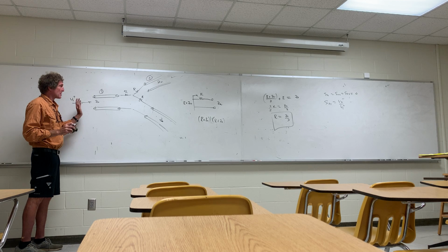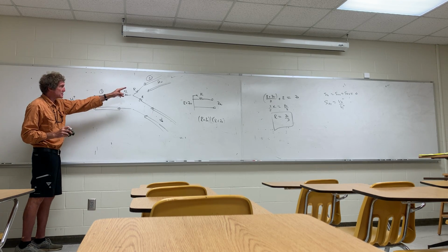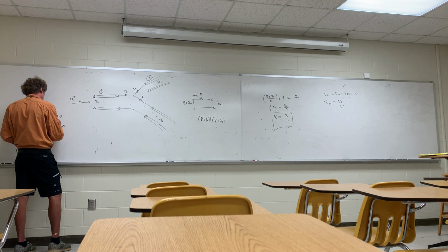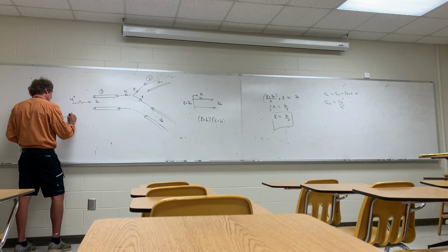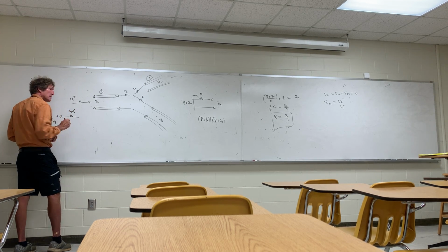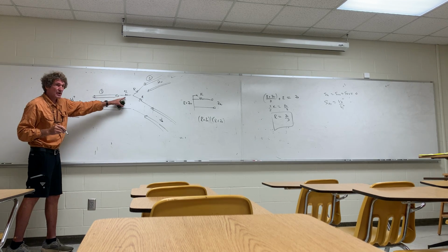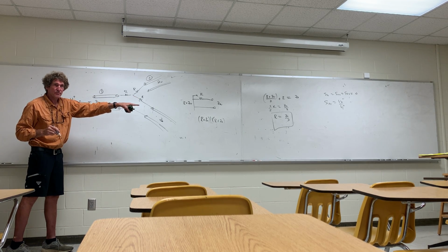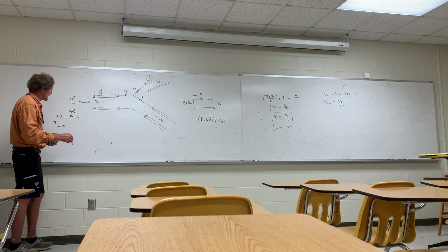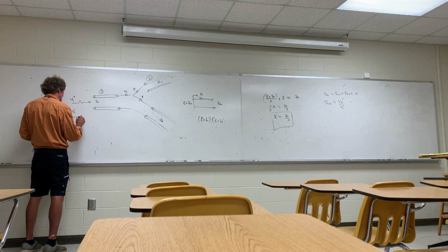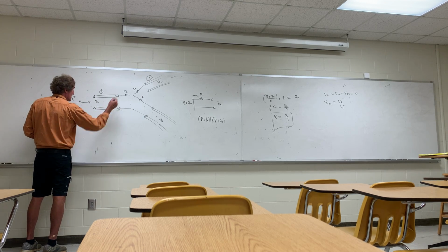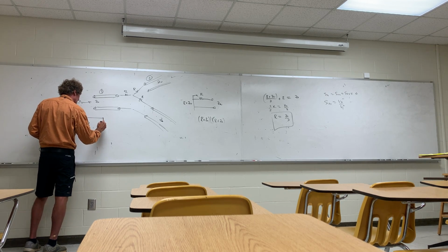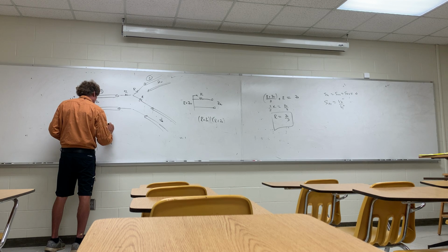So if I look here, and I think about this, I'm going to put resistors instead of Z naught there. Here's my port 1. I've got a resistor here, and the value is Z naught over 3, correct? That's this value, right? Because we calculated that value over there. Y'all follow me? That's what R would be for when we have just a two-way split. Comes to there, and then what do I have? Well, I have basically another Z naught over 3 in parallel with a Z naught over 3, right?